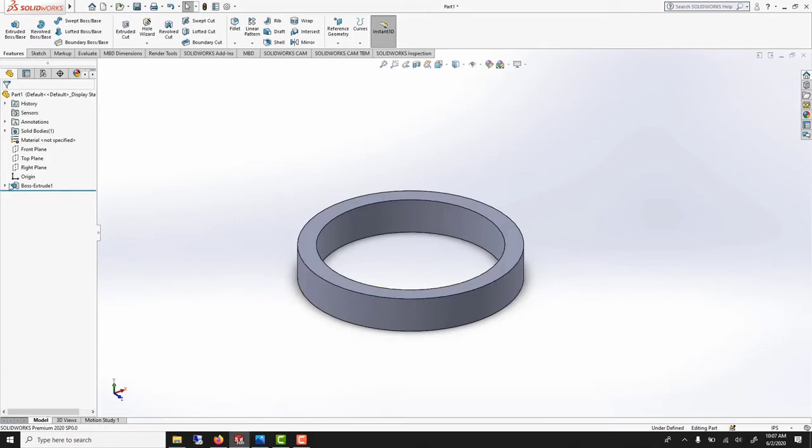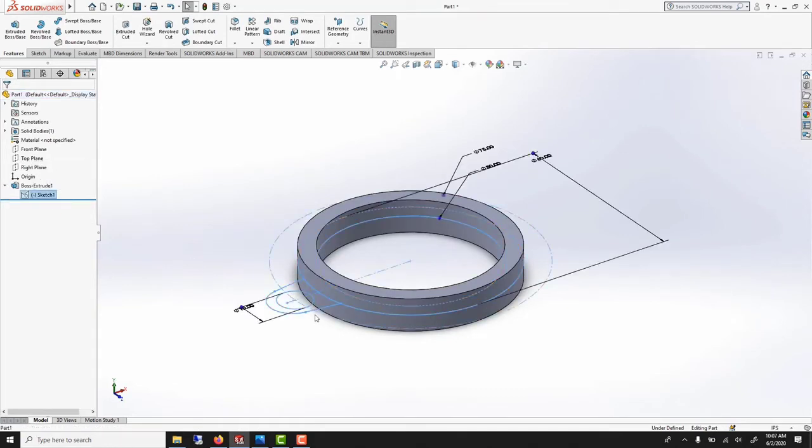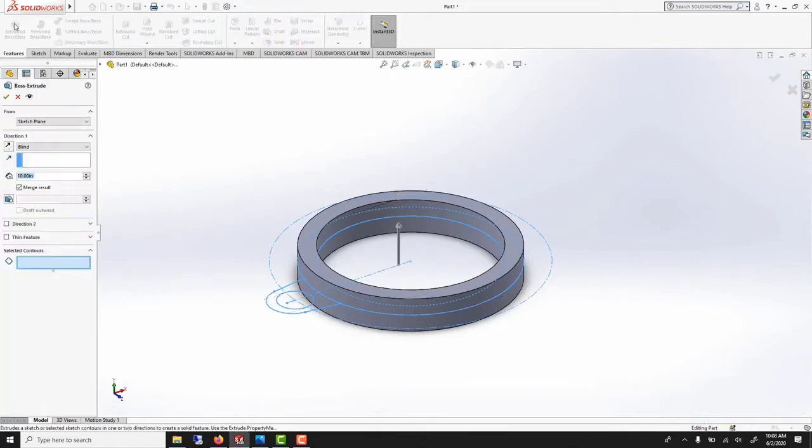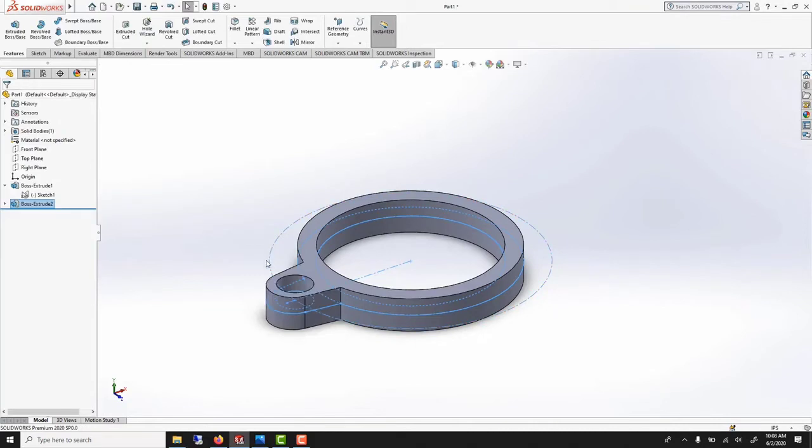And the reason I'm doing this is that I'll be able to extrude this one. So I select the sketch, extrude, and this time you can pick this one. So the result is the same, they'll merge, but you could just repeat the one you need. So mid-plane and the same 10 inch. So this is the selected contour function.